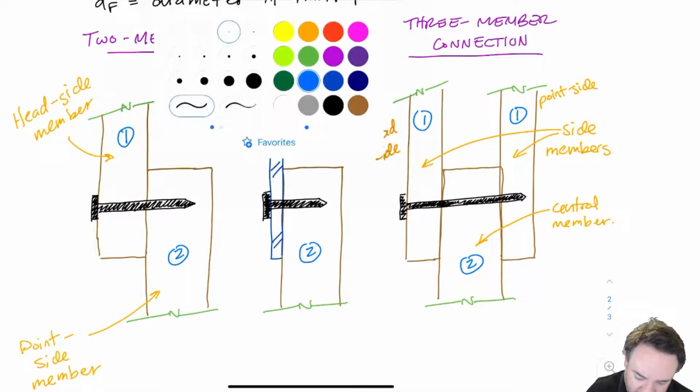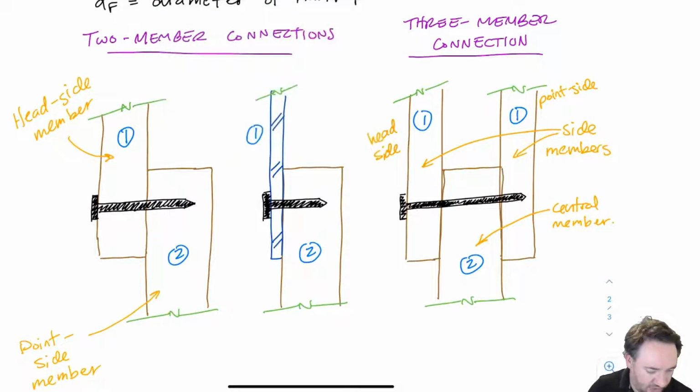Okay, so let's do that now. We have thicknesses and we have minimum thicknesses. There's a similar figure to this in the standard that lays out all the minimums for thicknesses. I can't put a nail through a sheet of paper, which is technically a very, very thin piece of wood. I need a minimum thickness in order for the nail to properly engage.